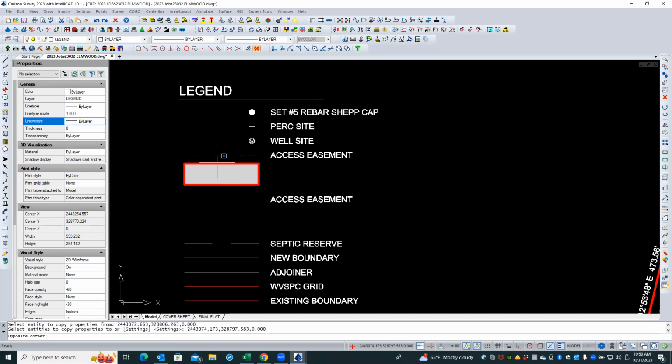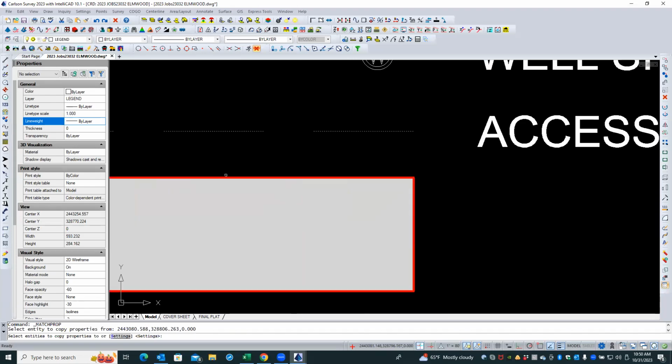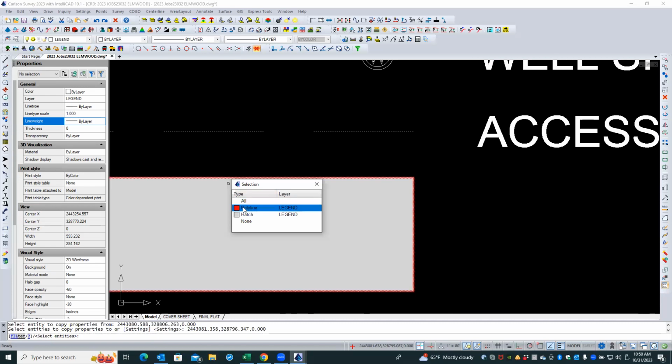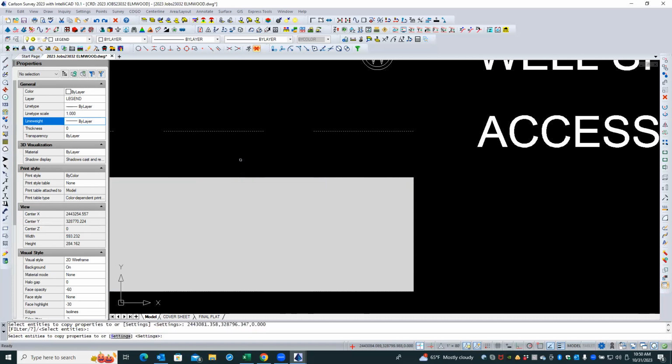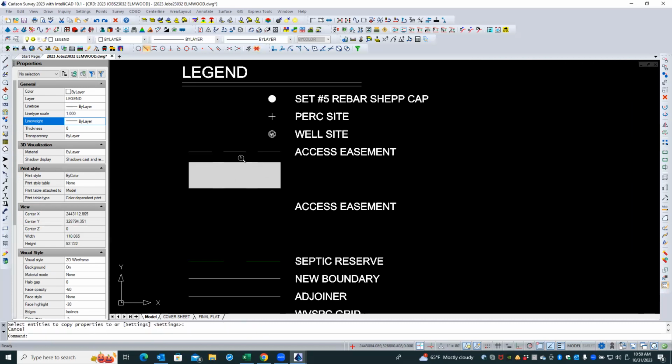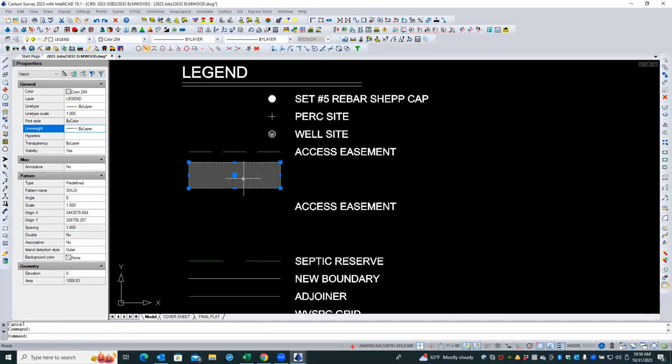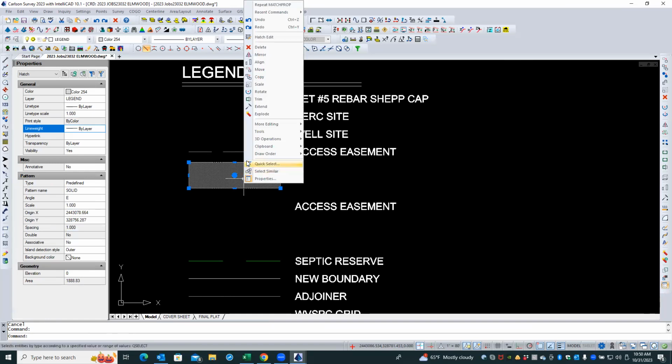Okay. Nope. Press escape. You missed it when you picked it. There you go. And so it started doing a window selection. All right, so click that. And then now, well, you don't have to get, yeah, there you go. And click and choose the polyline. Okay. Now I'd select your hatch and do a draw order on it. Make sure it goes to the back.